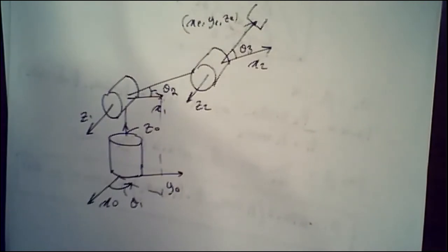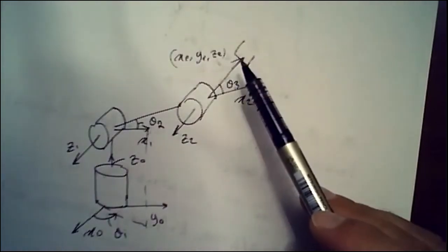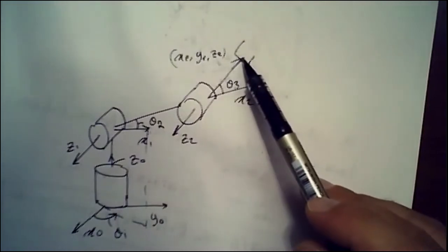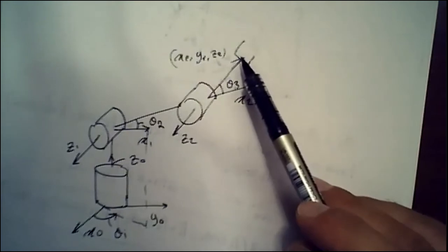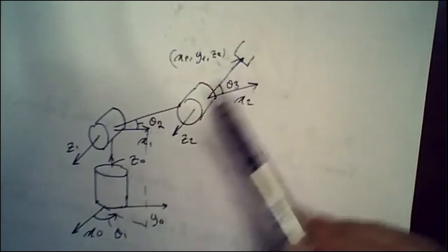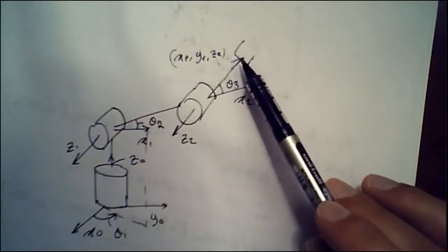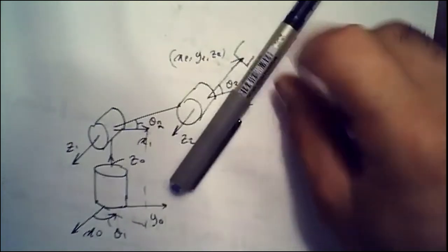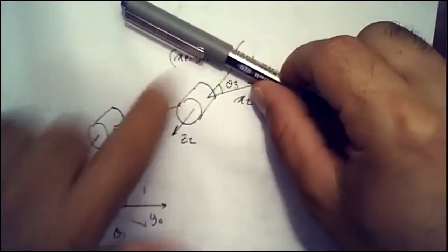Six axes will allow you to control the orientation of the end effector. Here, we are simply positioning this point. We have no control over exactly how this guy would look. There's only a single solution that would provide that. Or in other words, there are actually two solutions, elbow down and elbow up. But if the robot is holding this pen, I'm locked into this position, or that position, which is the elbow up position.